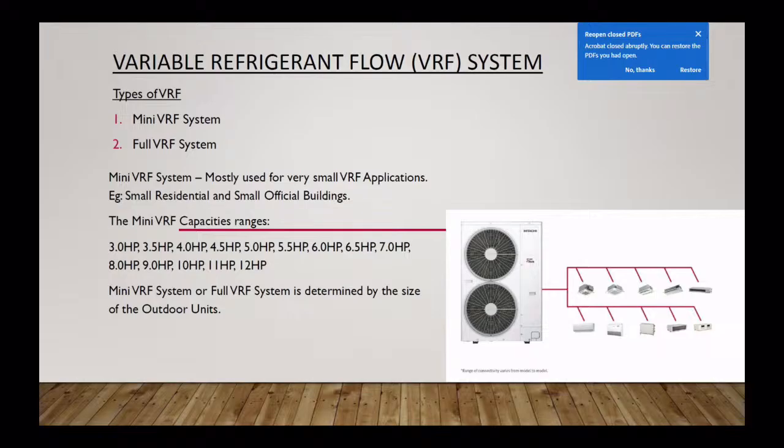Now, in the VRF system also, you have the mini one, which is used for small locations, like a small building with just a bedroom, two bedrooms, a sitting room and all that. You have one outdoor unit taking care of a few indoor units. So it ranges from 8 horsepower up to 12 horsepower. A simple system, outdoor standing, few indoors. The system ranges from 3 horsepower to 12 horsepower.